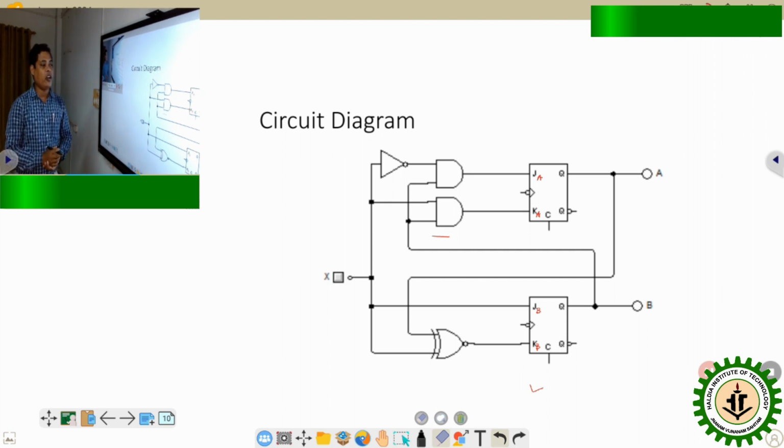Hence, if this kind of state diagram is given to us, by following the proper steps with the given JK flip-flop, we can find out the corresponding circuit. In this particular circuit, one thing is missing, that is the output Y. If it is also present in the state diagram, then additionally we need to find out the output equation by using the Karnaugh map itself, and we can draw the whole circuit not only with the states A, B, etc., but also with the additional output Y.